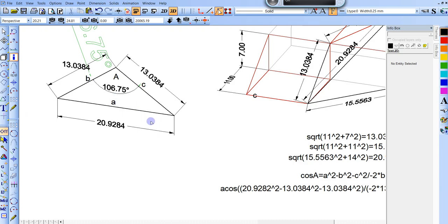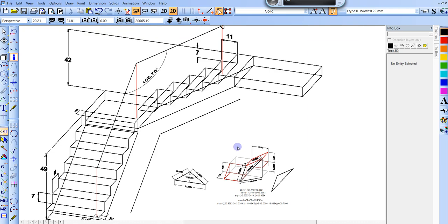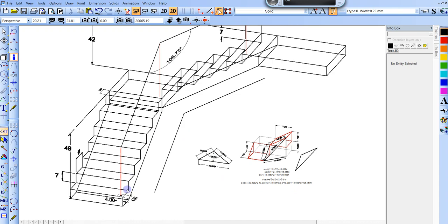All right. I hope that helps you understand a little bit better, and take care of making the handrail right, making sure you see that coming ahead of time. If they talk about a single miter handrail, make sure that the geometry of the stairs and landings works out. Your rails could be on the outside of those, and it would just change differently, but the angle would be the same. This angle won't change, but the geometry of the treads coming into the landing will change for sure.